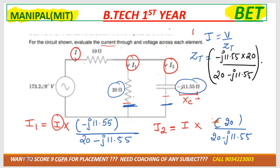We have solved this, plus this 10 ohm is in series. Correct? So you can multiply directly, or you can do it in rectangular or polar form. So from here we can get ZT. After calculation of ZT we can get the current, and after getting the current we can substitute it over here. Then we'll get the value for I1, and then the value for I2. So see, in 1, 2, 3 steps your question is solved. Correct? Now they are asking for the voltage across each element.